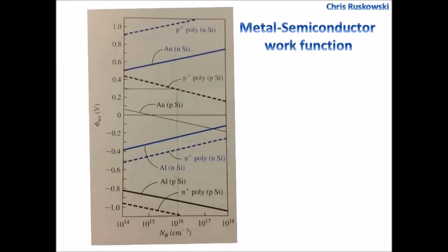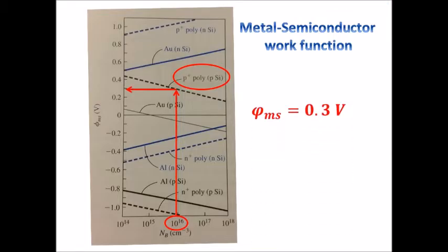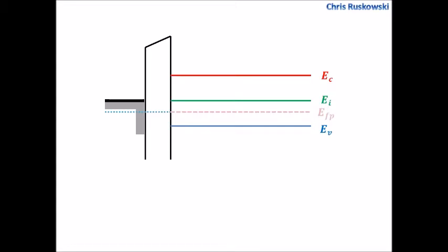This is a very quick, dirty, fast way. The actual derivation requires knowing the electron affinity and the energy states to the vacuum level for every single device, adding them all together, and then we will get close to what this chart references as well. Here, with the chart, our semiconductor work function came out to be 0.3 volts.